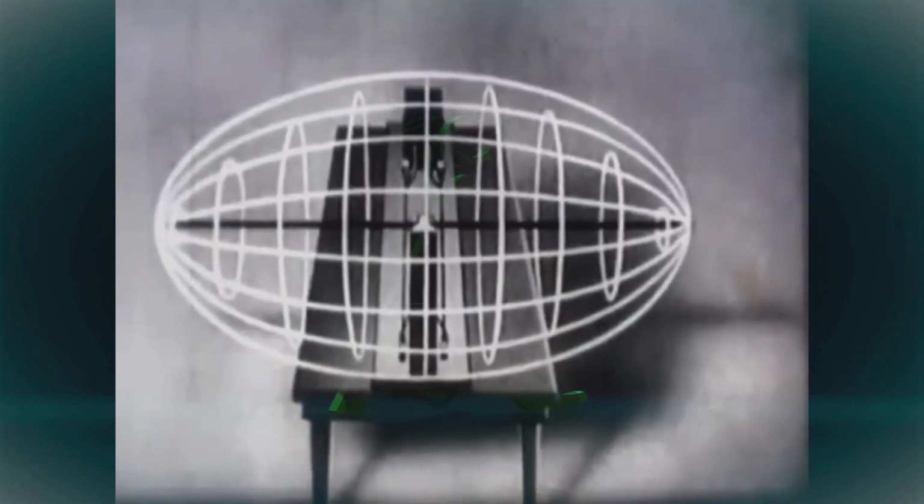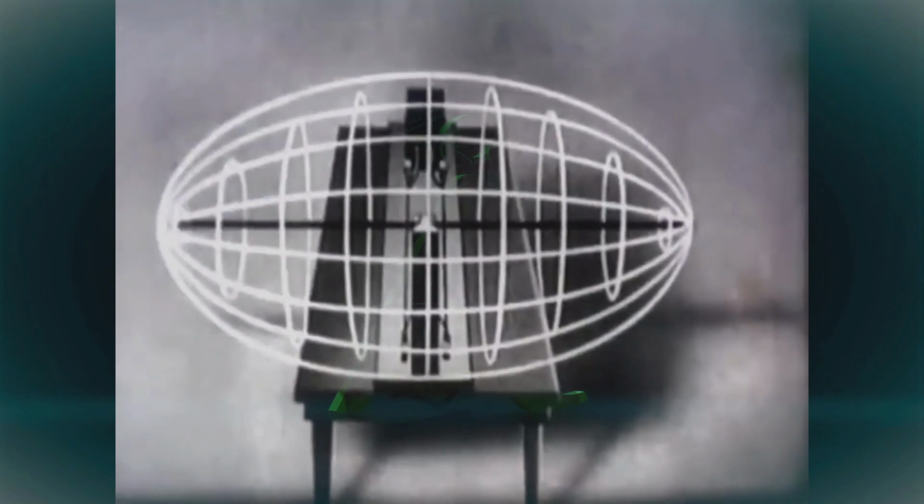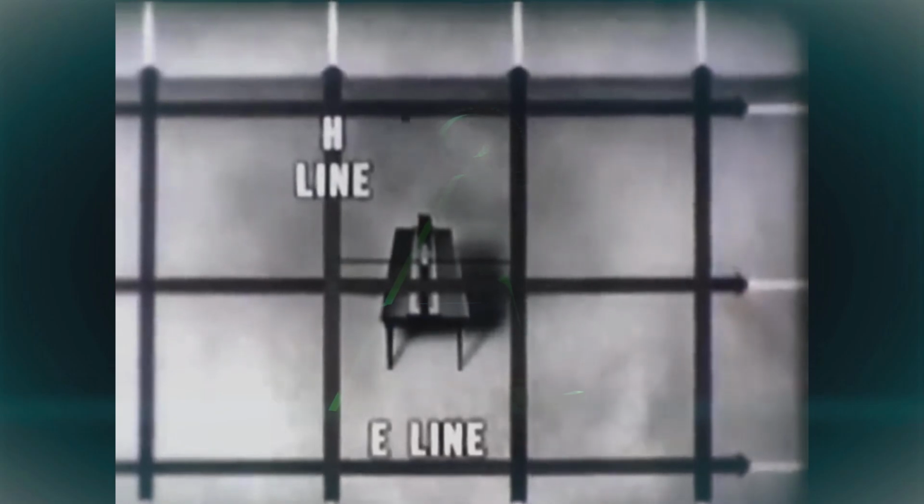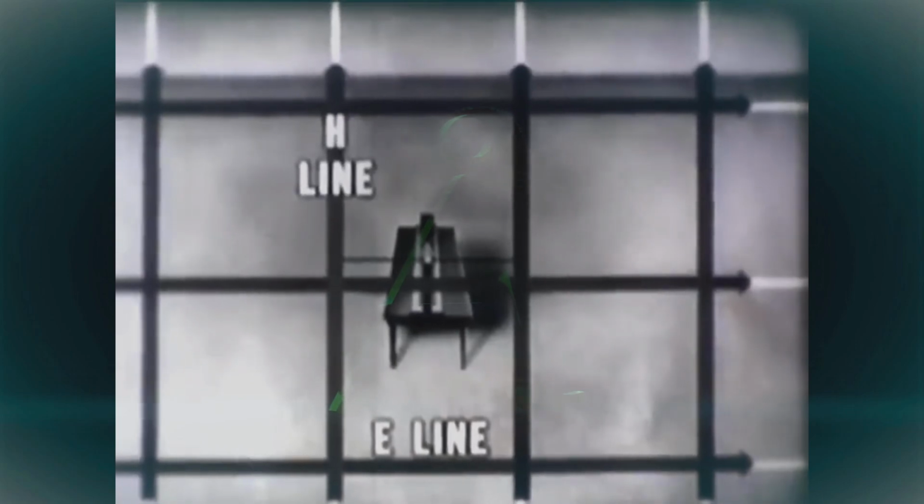Let's say these lines form a single wave, and we'll stick with this wavefront as it is radiated into space. Upon leaving the antenna, the pattern enlarges. It stretches, yet the magnetic and voltage lines retain a fixed relation to each other and to the Earth. For instance, stopping the wave, we see that the magnetic or H lines are still perpendicular to the voltage or E lines. Also, we see that the E lines in this wavefront remain horizontal or parallel to the Earth's surface. Because of the direction of the E lines, we say that this wavefront is horizontally polarized.